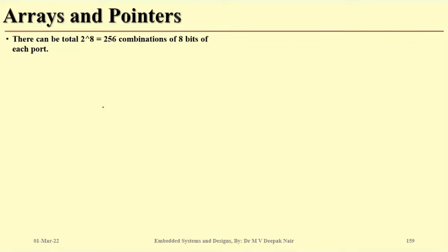And remember, we have discussed in the past also that these ports allow changing a single bit also. It is not necessary that I always have to throw all the 8 bits in that particular port. We can change even a single bit without disturbing any of the other bits. What I mean by that: for example, D6, D5, D4, D3, D2, D1, D0. If I am interested in only changing the bit at D4, be it 0 or 1, I can change it without disturbing any other bits.